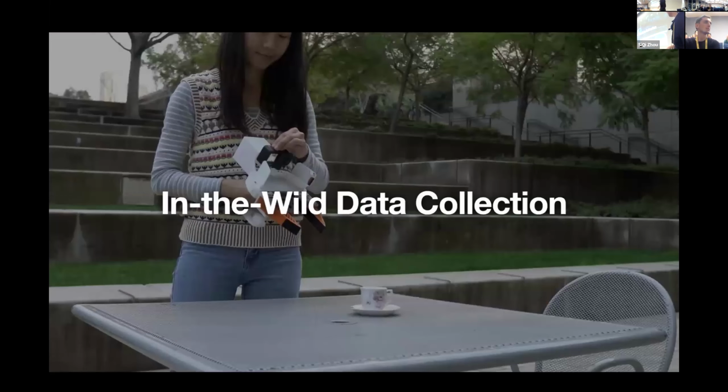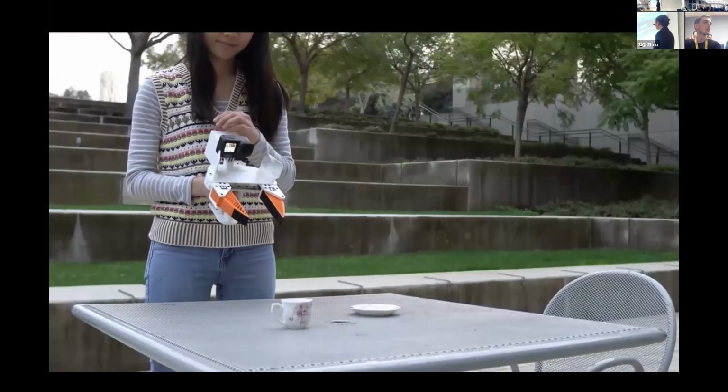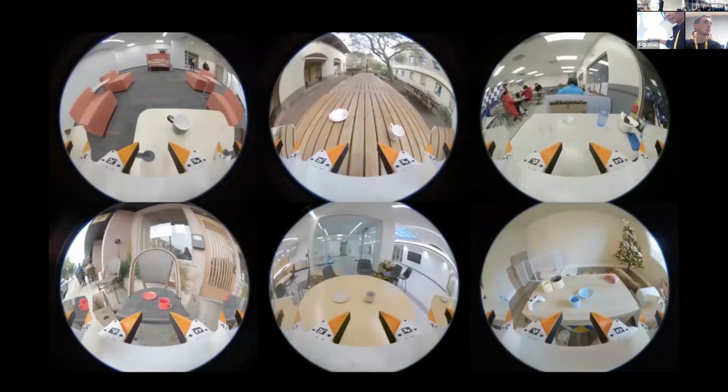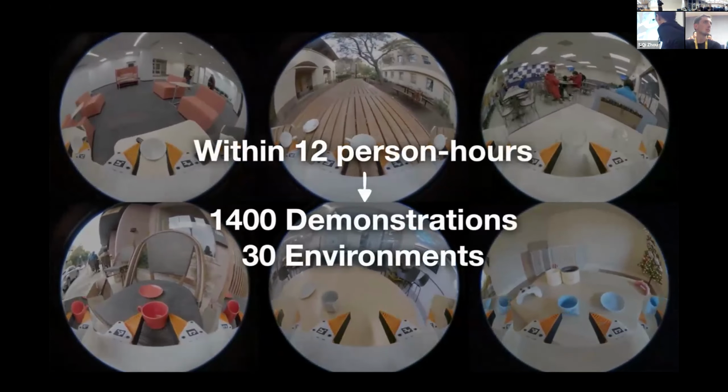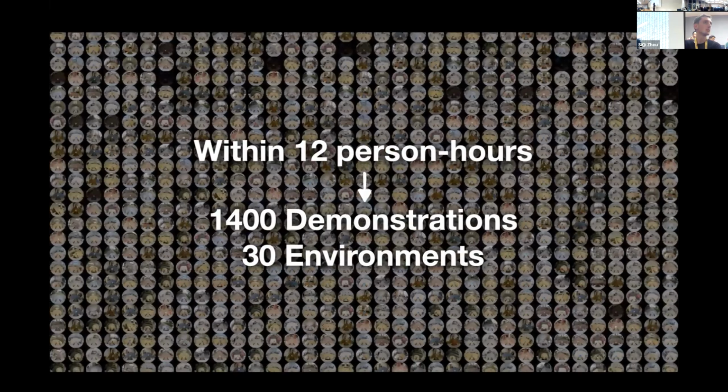But today I want to focus on a slightly different aspect, which is the portability of the data collection device, and as a result, it allows us to collect data in the wild, right? Because the system is so portable, the whole handheld gripper is very light and very small, you can carry it around into any different environment you care about, like your home or your kitchen, and collect the data that you care about. For this particular cup rearrangement task, we collected over 4,100 demonstrations across 30 different environments. In total, we only took 12 person-hours, which is quite short. If you have multiple people, that's just one afternoon to collect all the data. And then in the end, we trained one policy that covers all this training data.